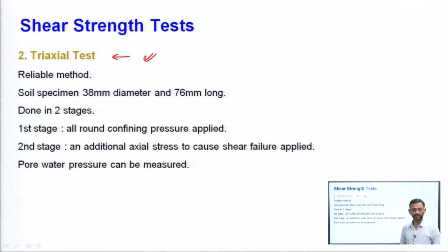This is a very reliable method, and the very first point here is an advantage, because we are trying to control the pore water pressure. When we can control the pore water pressure, we can simulate the field conditions in the lab itself. Then, when you can correctly analyze in the lab, you can apply it in the field with a very good approximation.